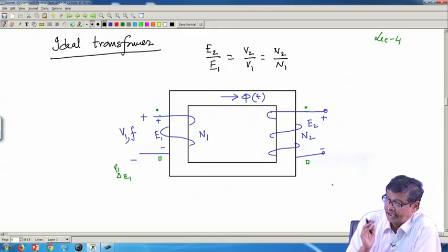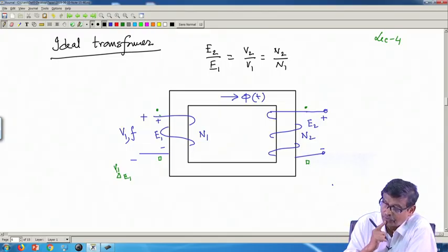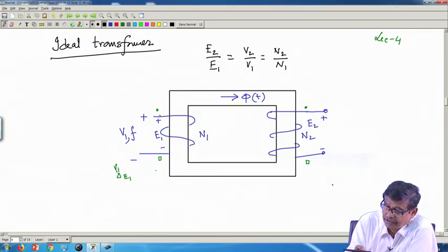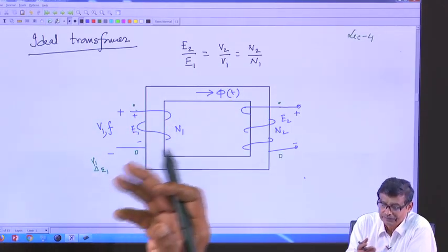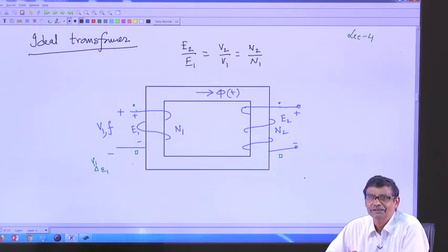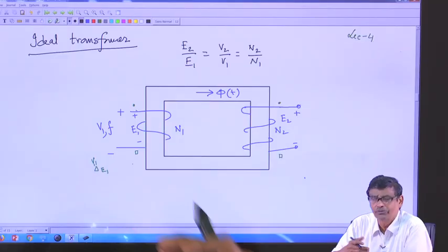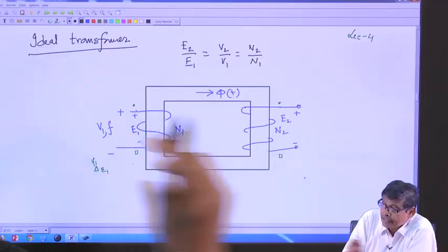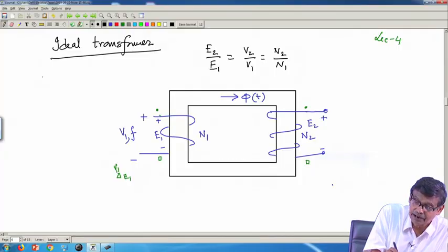Now, this is the thing, and then in my last class I told you how to draw the phasor diagram. You see, magnetizing current, with the assumption that there is no leakage flux and mutual flux only. So, this coil to this AC supply, this coil will appear as an inductance. What else? Because no resistance. See, essentially N1 dphi/dt is nothing but L di/dt. From your circuit analysis, you know, if time permits, we will dwell upon that. But the point is, if I want to draw the phasor diagram, I will do it like this.